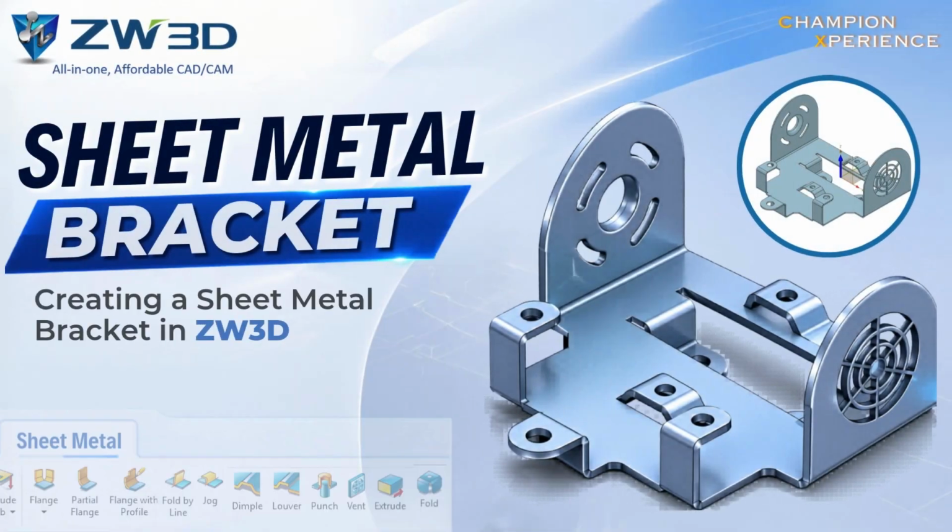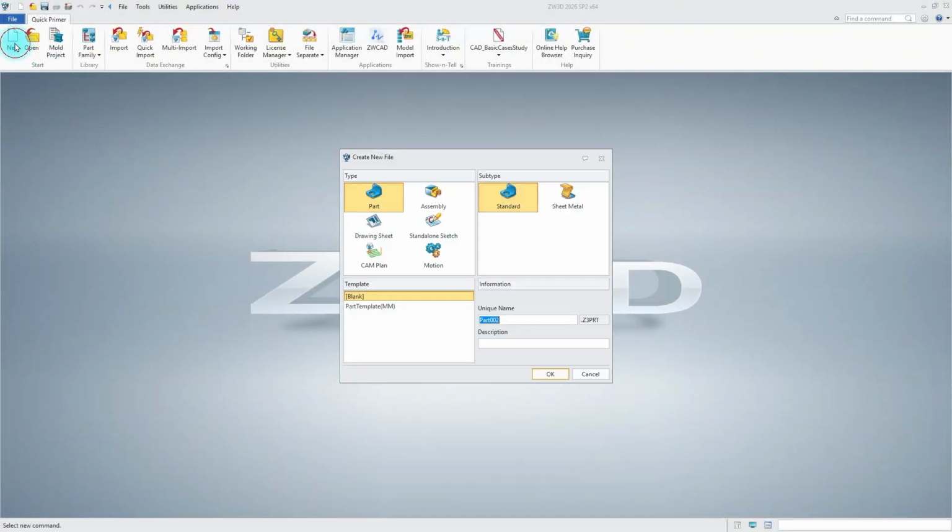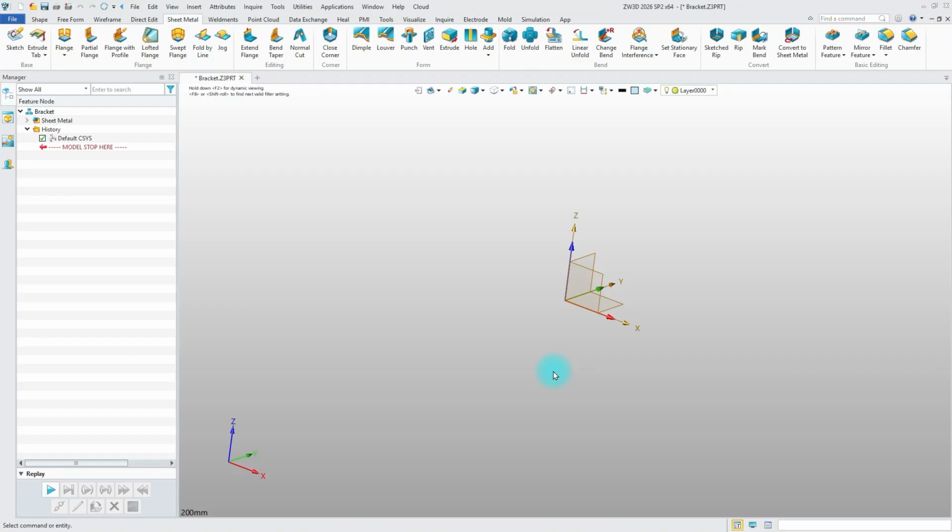In this example, we will create a sheet metal bracket in ZW3D using the sheet metal features. First, we launch ZW3D and create a new part file. After that, we switch to the Sheet Metal Ribbon tab and rename the part to Bracket. In the feature history, we double-click the Sheet Metal feature to edit the global parameters.